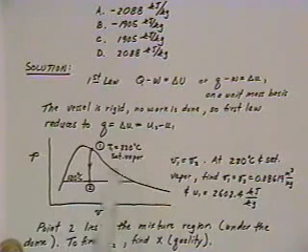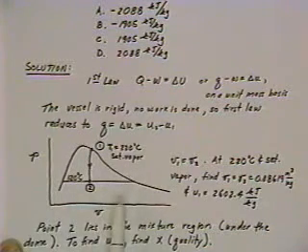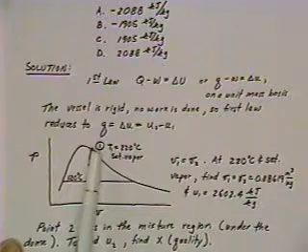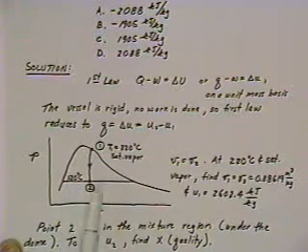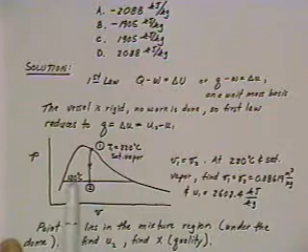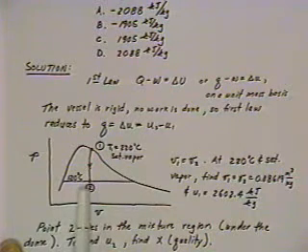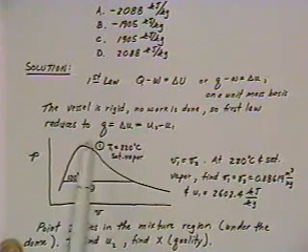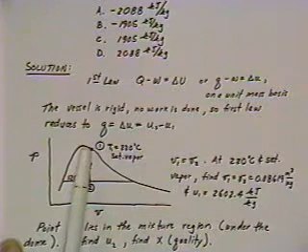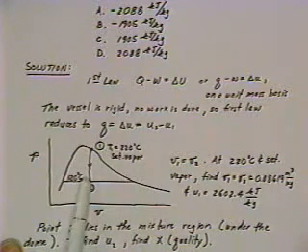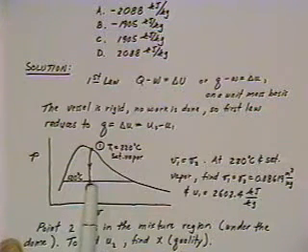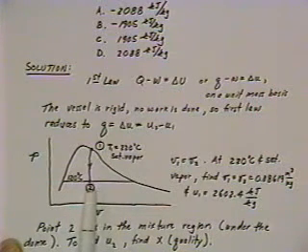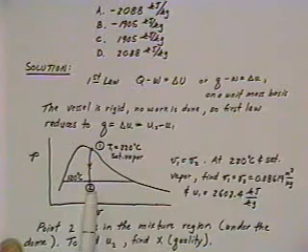So if you sketch out the process on the PV diagram, then you know that you're going from state 1, which is at 220 degrees C saturated vapor, down to state 2. State 2 is at 120 degrees C. Any time that you're starting out under saturated vapor conditions and you're cooling off, lowering the temperature, you're going to drop into the mixture region, so the point 2 here is literally under the dome. It's in the mixture region.